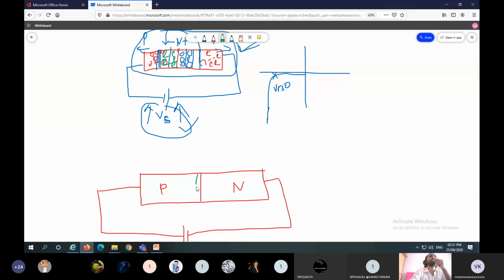There is some small depletion layer, and it will be overcome after the cut-in voltage or threshold voltage, and current starts flowing. Here the current flowing through the device is very low due to less charge density, and the power loss across the device is also high due to the high impedance offered because of low charge density.